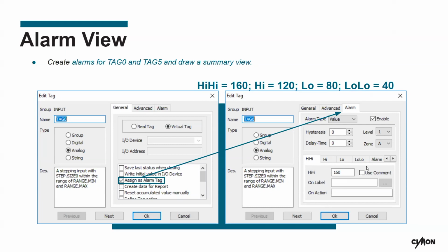But once you pass the high-high or the low-low, those are thresholds that you want to be notified of immediately, and you need to take action to change the route of your application to make sure no one's hurt or that nothing is passed. As an example, let's look at a water tank, right? A high and a low could be 80% and 20%. Those aren't very critical values, but the high-high and low-low could be 90% and 10% respectively.